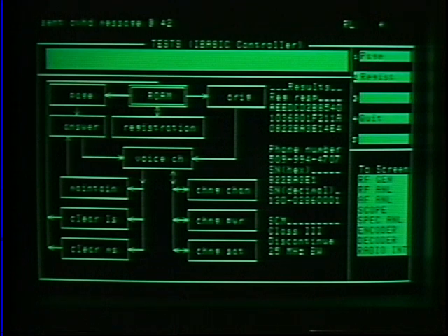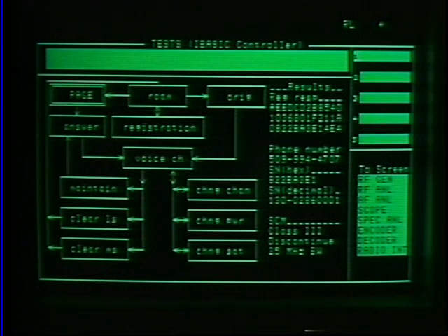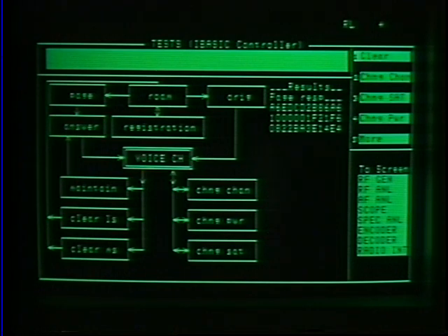Once it's registered, the flowchart program steps you through the call processing procedures required to get a mobile onto a voice channel. To page the radio, choose K1 page, and the 8920 will automatically ring the mobile and then expect an answer back to move to a voice channel.